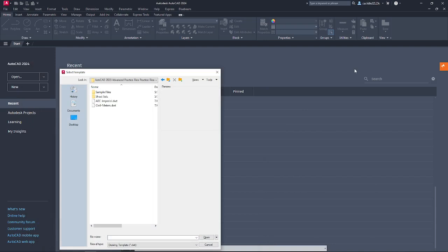In this practice, you will create a standard file that is based on a template and associate a standard file with a drawing. You will also check a drawing for compliance to standards and fix any discrepancies. In this task, you will create a standards file based on a template.